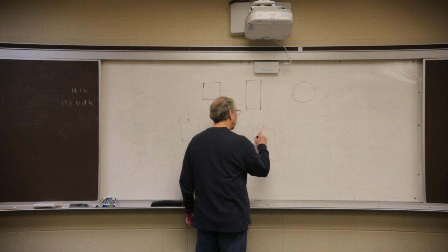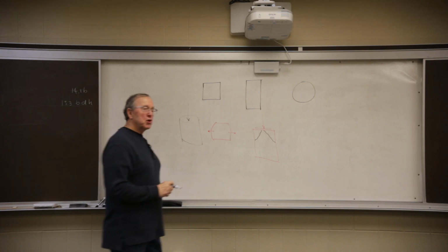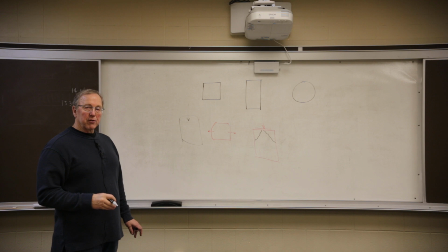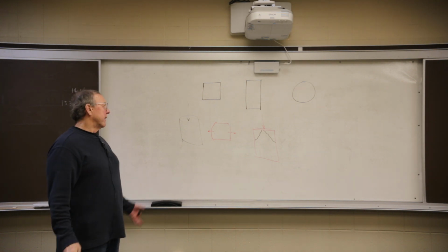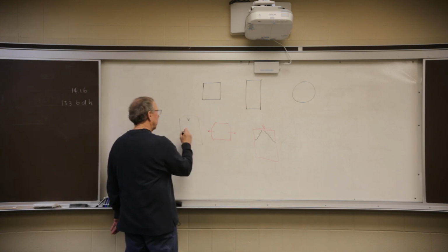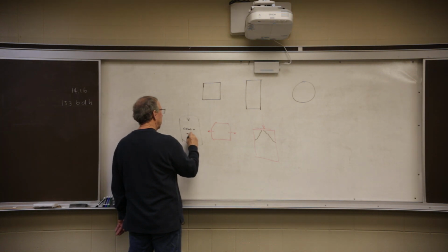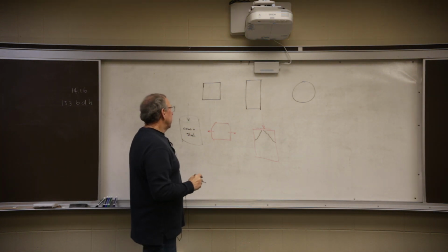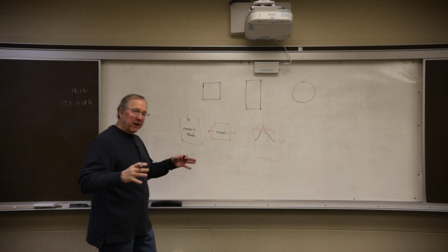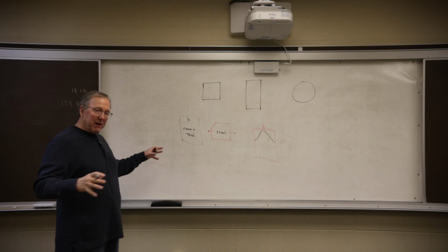And shear means the corners of the concrete push hard enough that it actually pushes the corners off. And then the area keeps getting smaller. As the area gets smaller, the stress gets bigger, and then it'll just basically crumble. So this is a function of concrete and steel. They take up the load. The steel tends to hold the thing from ballooning out, turning into a marshmallow that's being flattened.